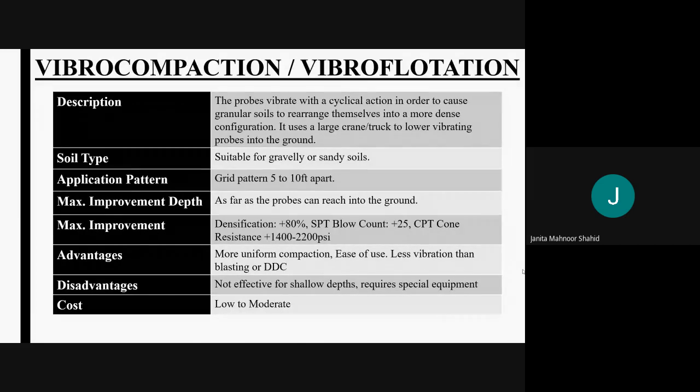So let's begin with vibrocompaction and vibroflotation. It is a technique which densifies the granular soil by insertion of heavy vibrating probes up to a desired depth, usually 150 feet or maybe beyond that. This probe is also called a depth vibrator or vibrofloat.